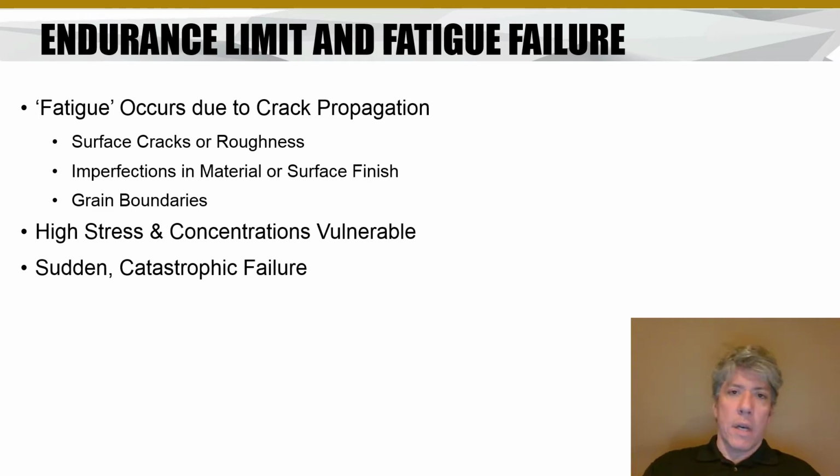Now, the areas of the material that are particularly vulnerable to fatigue are areas where there's very high stresses and also where there are concentrations of stresses, because stress concentrations generate high stresses in a very localized area. So those are the areas that are vulnerable, essentially just high stress areas. And the issue with fatigue is that it can cause sudden and very catastrophic failure where you don't expect anything.